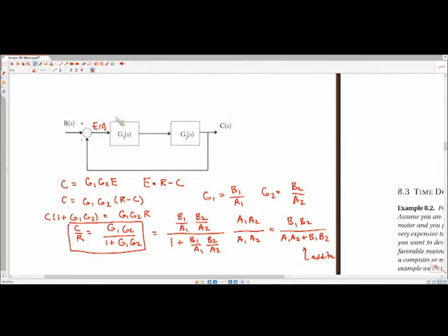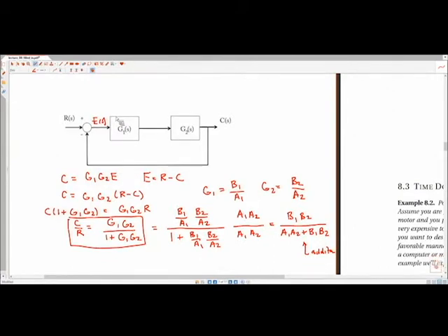All right. So we talked about the idea that if we have poles in the right half plane, that's going to result in an unstable system, or that's going to correspond to solutions C that explode in time. In general, our idea is that we're going to make sure that all our poles are in the left half plane. So if you remember one thing from this class, it should be that when we're designing control systems, we want all the poles to be in the left half plane. We want stable solutions. That's like a bare minimum to pass this class.